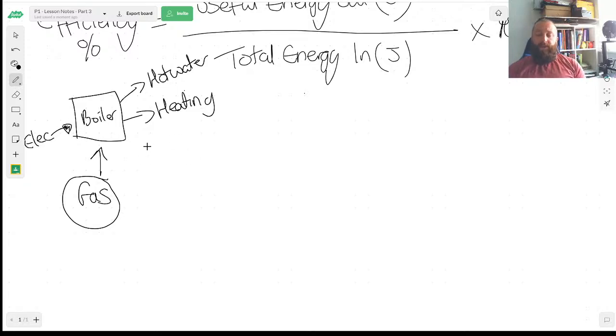And when that boiler is turned on, it will have a heat exchanger in. The water is going to be running through that heat exchanger, and the gas is going to be burnt to create flames, and those flames are going to be heating up the water. And that's what's going to give me the hot water, and it's also what's going to increase the heating. Now, the reason I need my boiler replaced is, one, they stopped making parts for it back in the 90s, but two, my boiler is only about 55-ish% efficient.